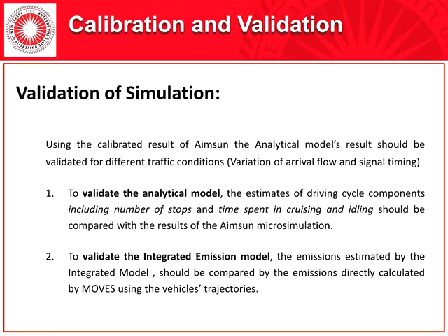Also, to validate the emission volumes estimated using the integrated model, the emissions calculated by our model, which applies the emission factors to the analytical model's result, can be compared with the emission volumes calculated directly from the project level of MOVES using our vehicle's speed profile.